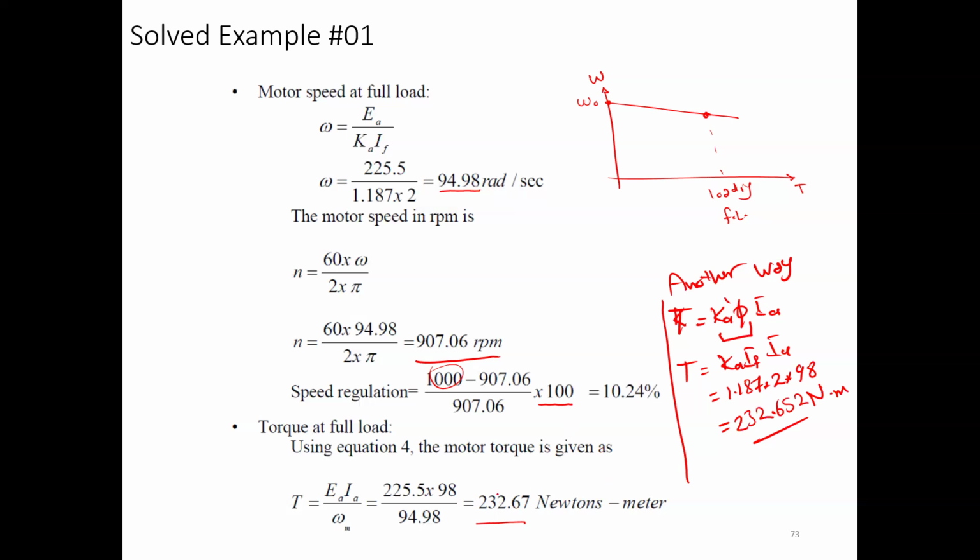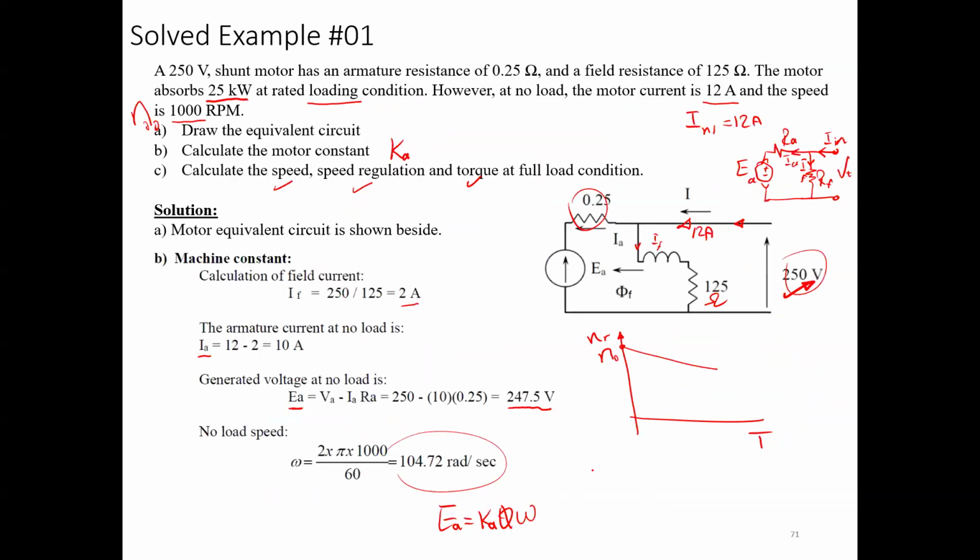And by the way, most probably, guys, the error in these calculations, as you can see, is in hundredths. So this is just because of rounding some numbers on the calculators. Okay. So here, guys, in this example, the difference compared to the previous examples was that the no load condition was given exactly. So we didn't say that at no load induced volt equals terminal volt. Why? Because we have the full data. Since the full data is given, you can make an exact solution.